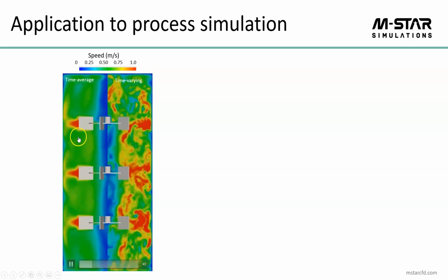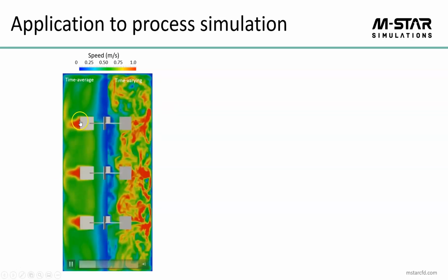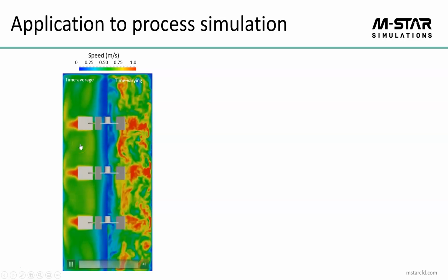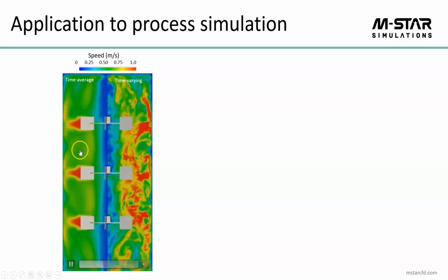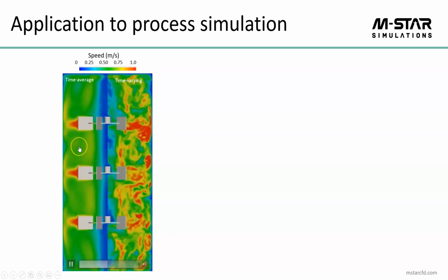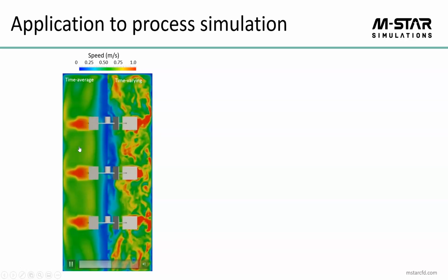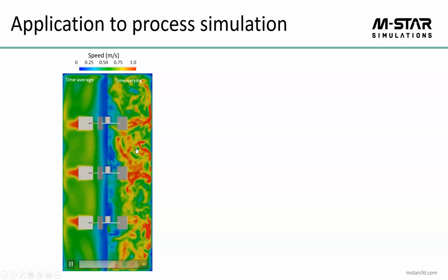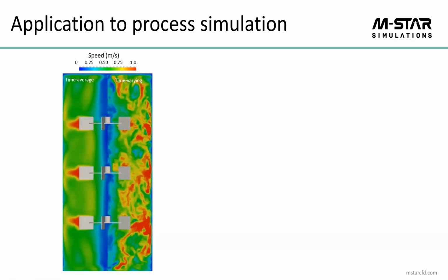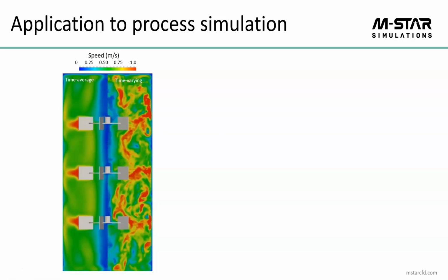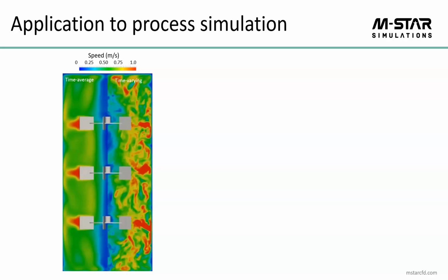Likewise, the time average solution says that between the impellers, there's this nice, oddly green mid-range velocity. That's not true at all. What's actually happening there is a large range of velocities being realized, as it were. And a cell doesn't see green, as it were, or some sort of mean flow field.